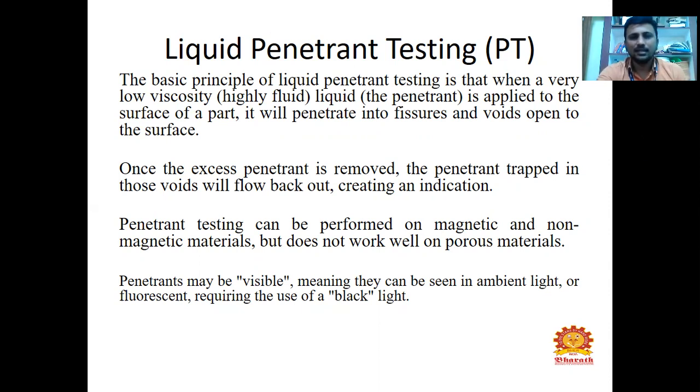Once the excess penetrant is removed, the penetrant trapped in these voids will flow back out, creating an indication. The penetrant test can be performed on magnetic and non-magnetic materials, but does not work well on porous materials.